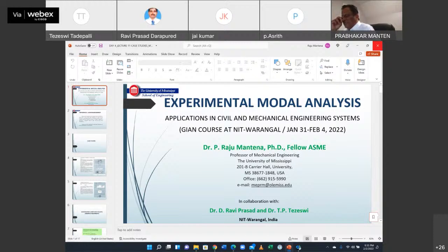The width of that peak at 3 dB, given in terms of frequency, omega 2 on the right side, omega 1 on the left side, divided by omega n, gives you the loss factor at that maximum energy. So that's why the concept of 3 dB. Again, this comes from signal analysis of electrical signal content, and all of that is focused around the so-called 3 decibel drop level. That's the real content level.